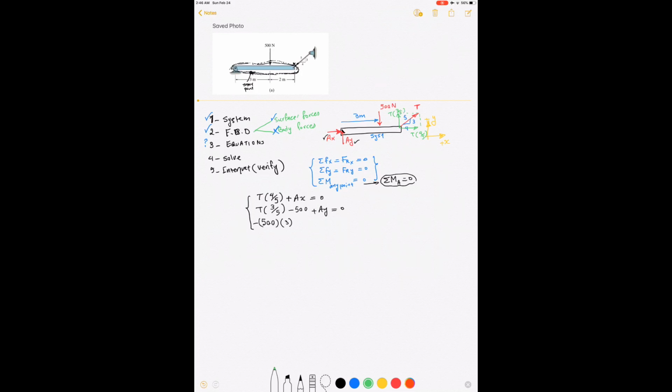So these are the two components. Now let's work on the X component. You see that its line of action is passing through point A, so its moment is 0. So we just get the moment from the Y component, this guy, right?